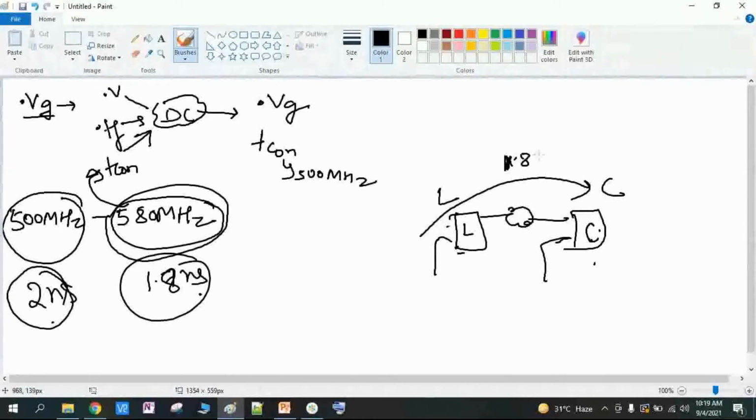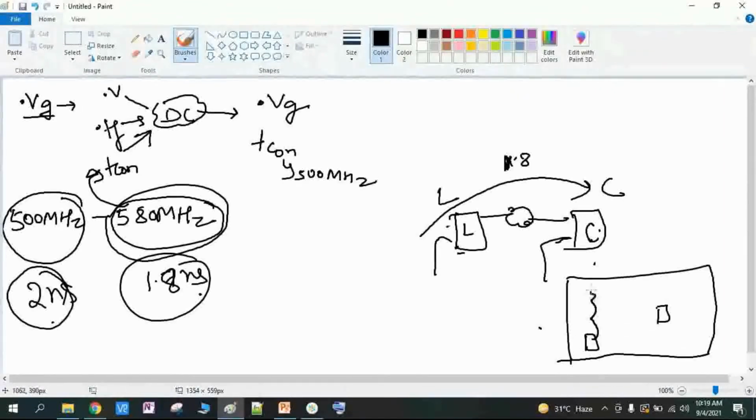Okay, let's say in the design cell, that means in the tool, when my logic is placed here and my logic is placed here, the wire, the net, is something like this, it has detoured. So if this is a very long net, then I'm not going to complete everything in 1.8, right? You got the point? Yes, sir. So at that time the tool will try to improve the transition time.